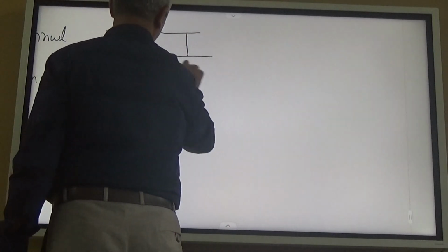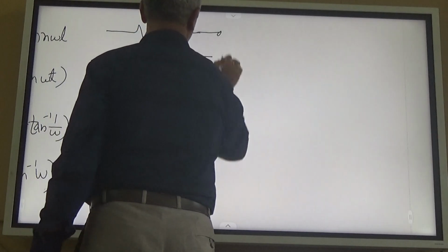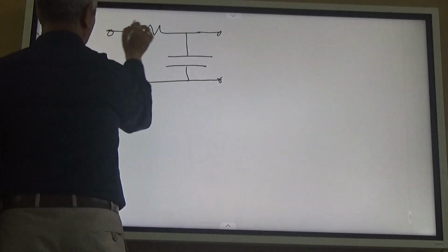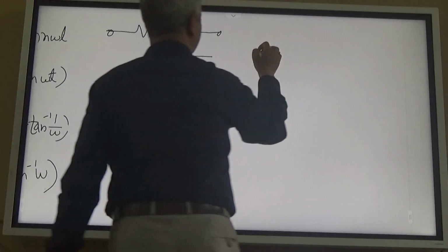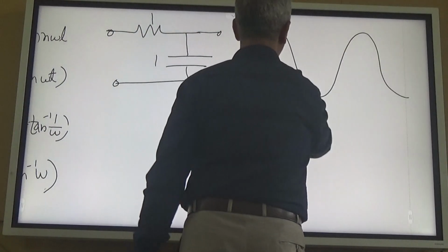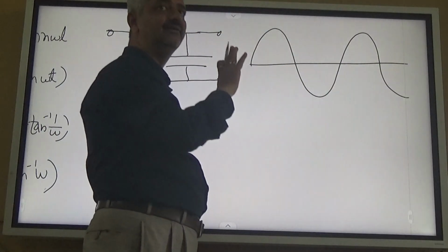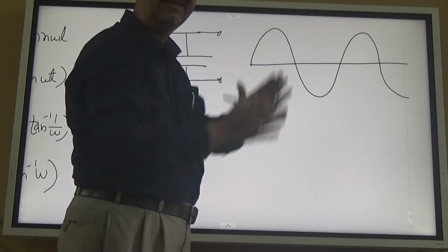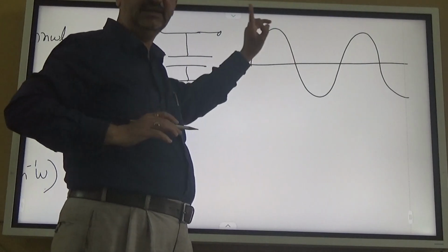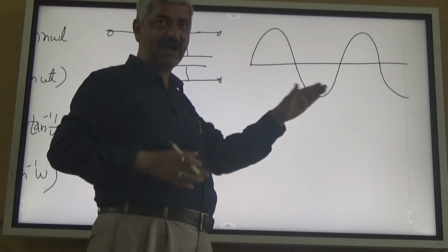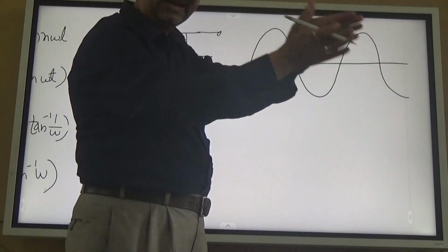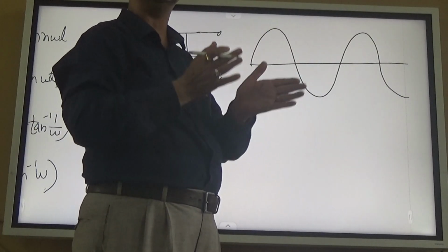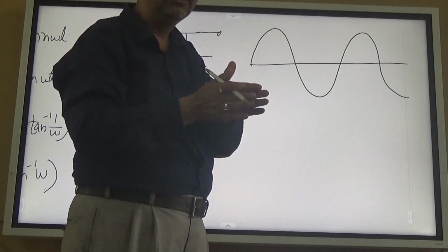Later on, extending it further, you can plot, you can use a computer utility. Now there are so many animation programs, you can pick one of them. You can plot the input and output would be an attenuated and phase shifted sinusoid. Input of frequency omega, output is an attenuated and phase shifted sinusoid of omega. The attenuation will depend upon omega.